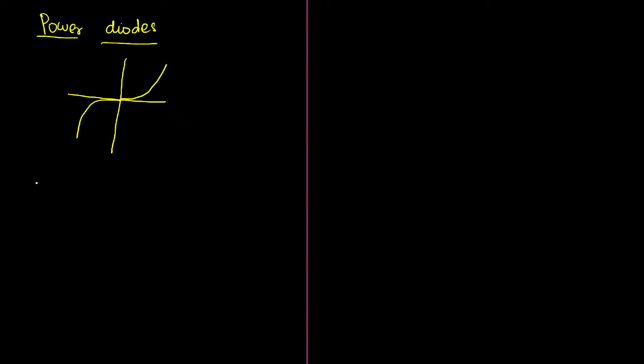But if you focus, okay, sir, in power diode, there are two regions. One is forward bias region and another one is reverse bias region. And if you observe in forward bias region, there is a small region that is called cut-in zone. After that, your diode will immediately switch on. So this is basically diode voltage-current characteristics. Yes or no? In the x-axis, we will be keeping voltage. In the y-axis, we will be keeping current, and the cut-in voltage of the diode is normally 0.7 volt. This is the minimum amount of voltage that is required to turn on the diode. Okay, sir.